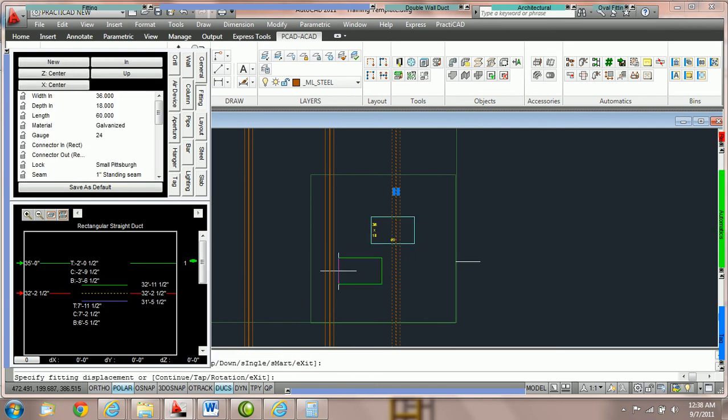And if we wanted bottom of duct to be 5 foot above the slab, I could say bottom of duct 5 foot. So generally we use the top as a reference point from relative top, and we use the bottom here as a reference point from relative bottom. These are usually the two values we focus on.